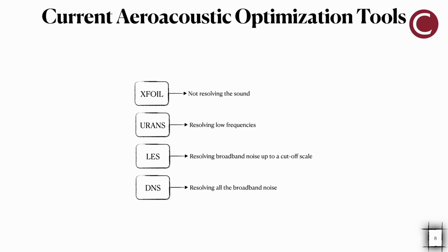And we can use that wall pressure spectra as inputs to Amiet's theory and then compute the far-field noise. There are so many different papers on these methods. So as I said, XFOIL doesn't resolve this sound. And if we need more accurate simulations and more accurate results, we need to use CFD simulations.